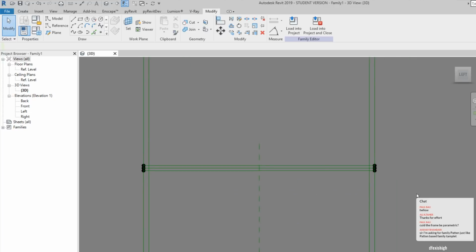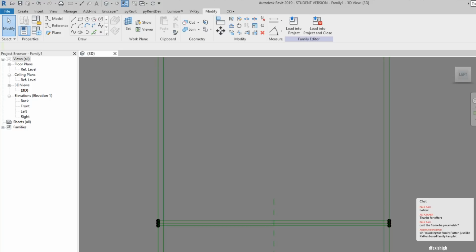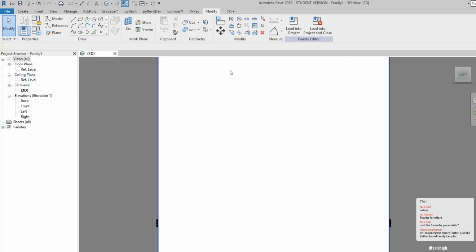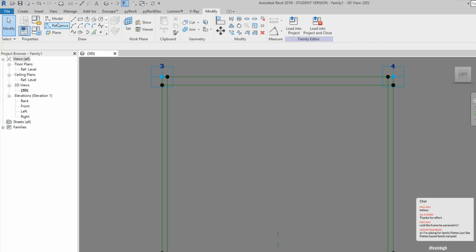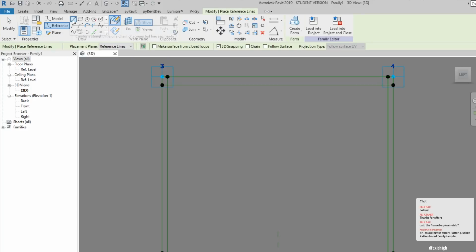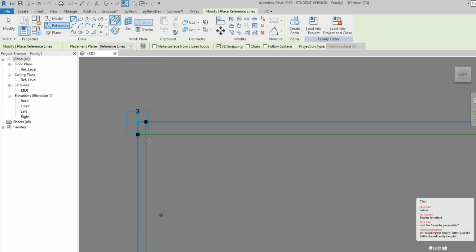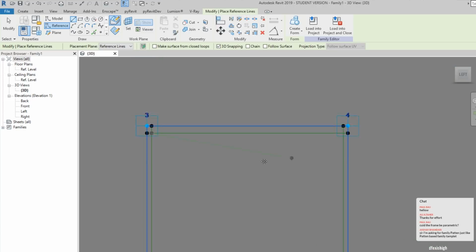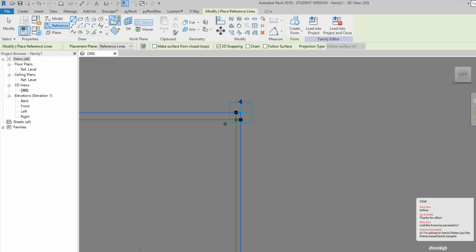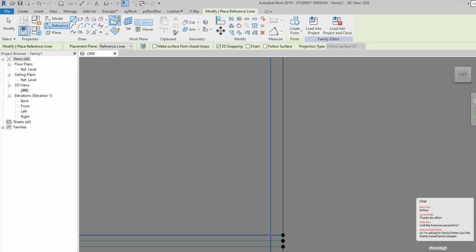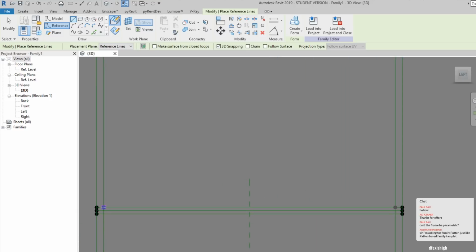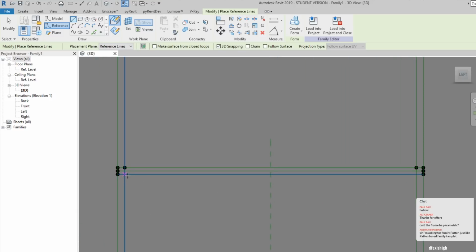So what I'm gonna do now, because we have the solid form, I want to create an opening here, and here I want to create an opening, right? So let's go back to the wireframe mode, and let's go to the references, and here we will find the line. And now I'm using that from here to that side, from that side to that side, and one more here. Let's close it, and let's create on this side too. Everything the same.